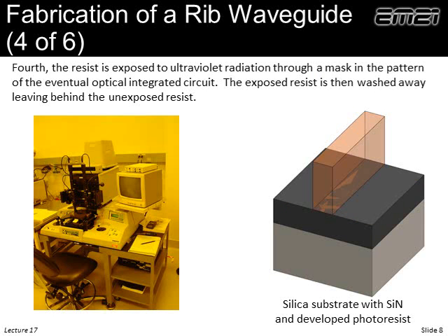So we do that. We put a mask over top. We expose through the mask, so there's shadow regions and bright regions. And depending whether it's negative or positive, we can do whatever pattern we want. We can expose it, we wash it away in developer solution. And so, for example, maybe out here, if this was a negative resist, wherever the photoresist did not see light, it would wash away. And this region here that did see light remains behind,